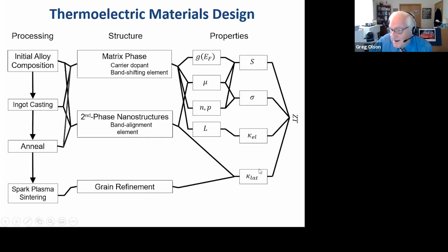And the way to break that is to use microstructure for phonon scattering to get the thermal conductivity down. So it was a chance to use the same kind of hierarchical microstructures that we use in structural alloys of precipitation and grain refinement to manage the thermal conductivity.